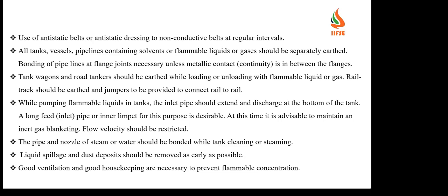The liquid spillages: if it is a solvent, what will happen? It will accumulate. Wherever a solvent spills, it evaporates and creates a flammable atmosphere. Or dust deposition, in case it is flammable dust, there is also a chance of fire and explosion. So whenever liquid spills or dust deposits accumulate, they should be cleaned regularly. Then good ventilation and good housekeeping are necessary to prevent flammable concentrations. Good ventilation.